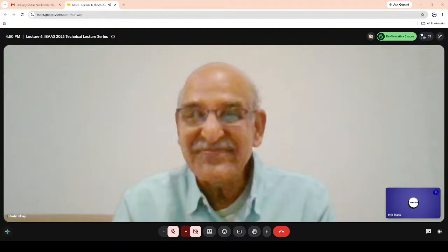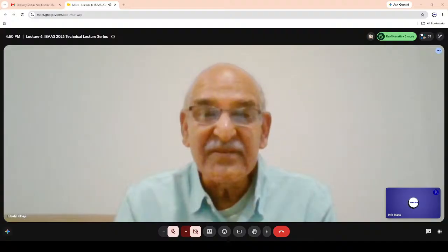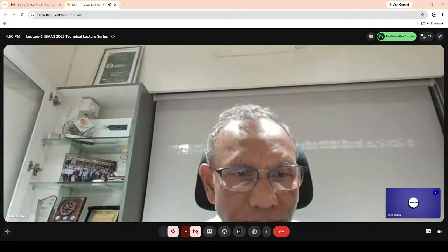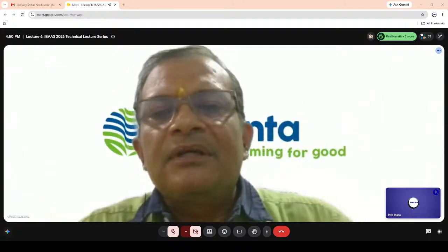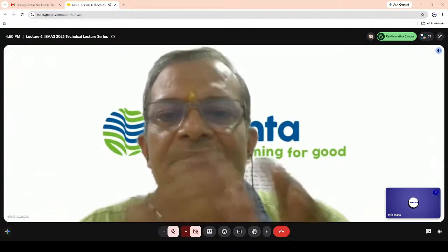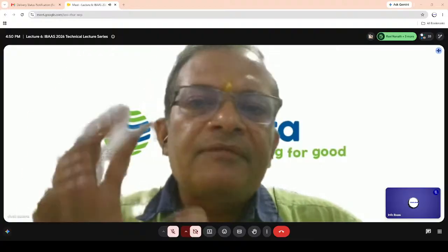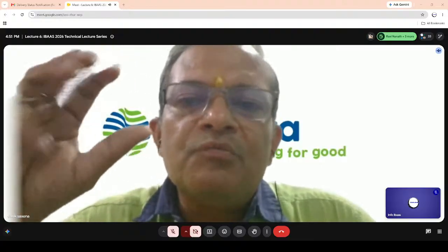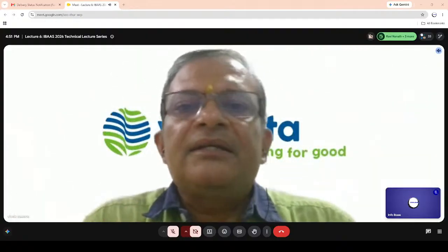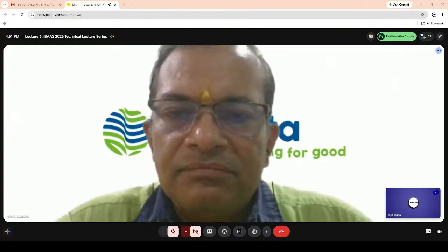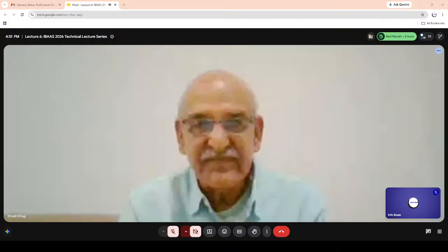Sir, can I add? Yes, Vivek. When you are operating the drum magnet, the angle at which it is scraping out needs to be checked from time to time. Sometimes it happens that coke goes away along with the metal. But if the quantity of coke is more, then you can use finger magnets or suspended type magnets to eliminate that iron, and then you reuse the coke. That will be very fine. Yeah, excellent.